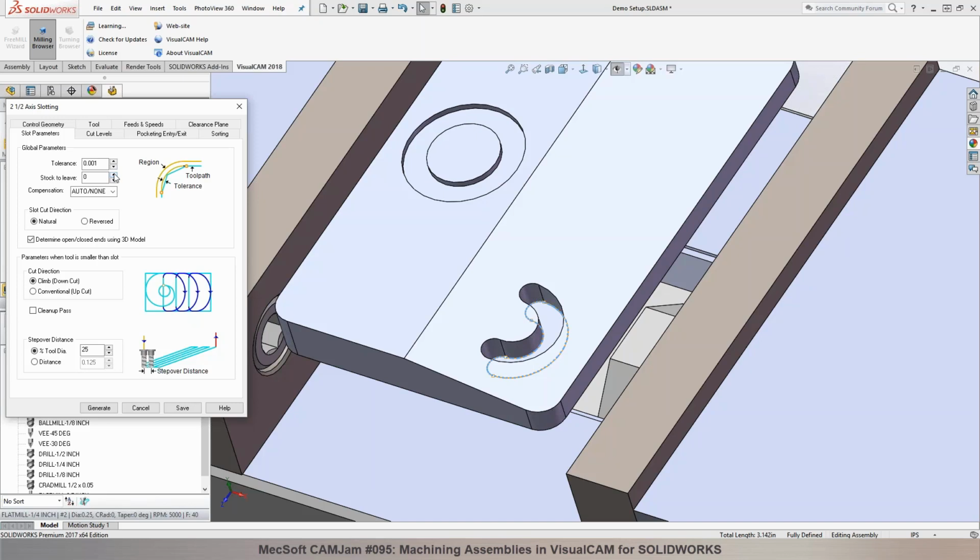In Visual CAM, all the toolpaths are generated based on the tool tip. The tool length and information that you put in is going to help you for simulation purposes. So as long as you're doing the touch off, you zero the tip at the machine, you'll be fine. Yeah, okay. That's what I thought. That's good to know.